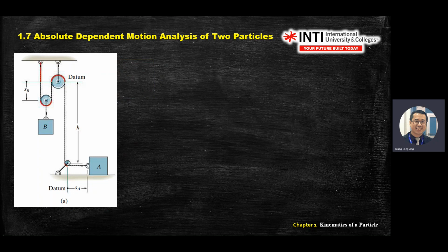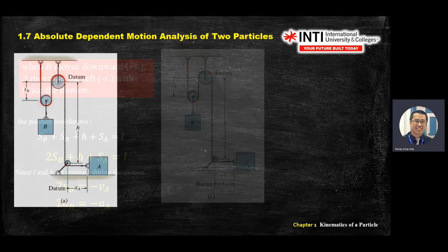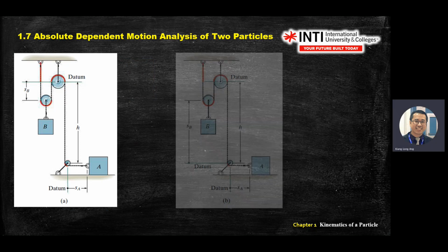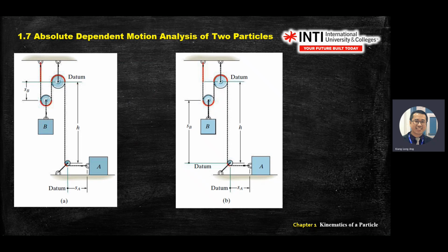Right? Okay. So now what happens is you change the datum. Look at A is what you saw just now. B. Can you observe what is different now? Anything different from A and B? B is different. Same setup. Datum now changed. Will you observe one of the datums has changed already? Datum B is measuring from the bottom rather than the top. B is positive, go up now.